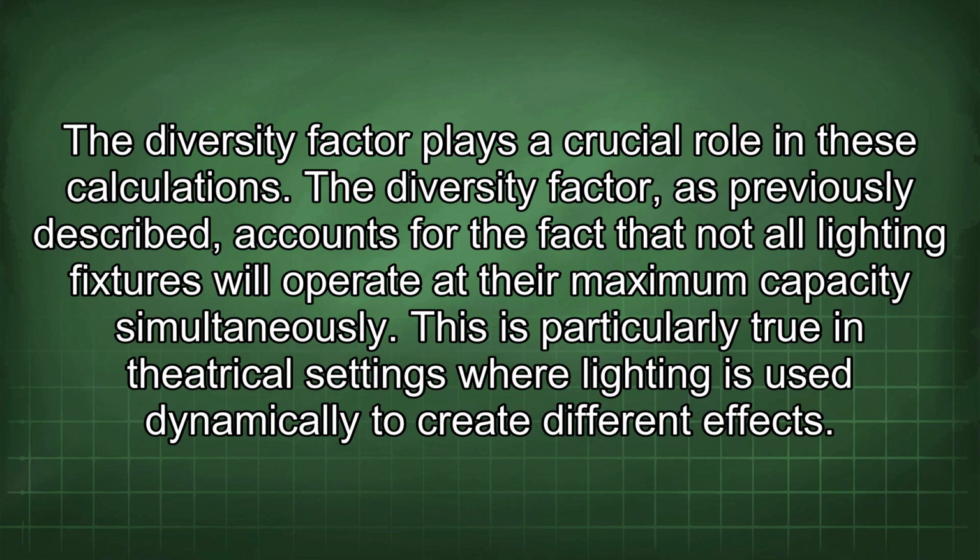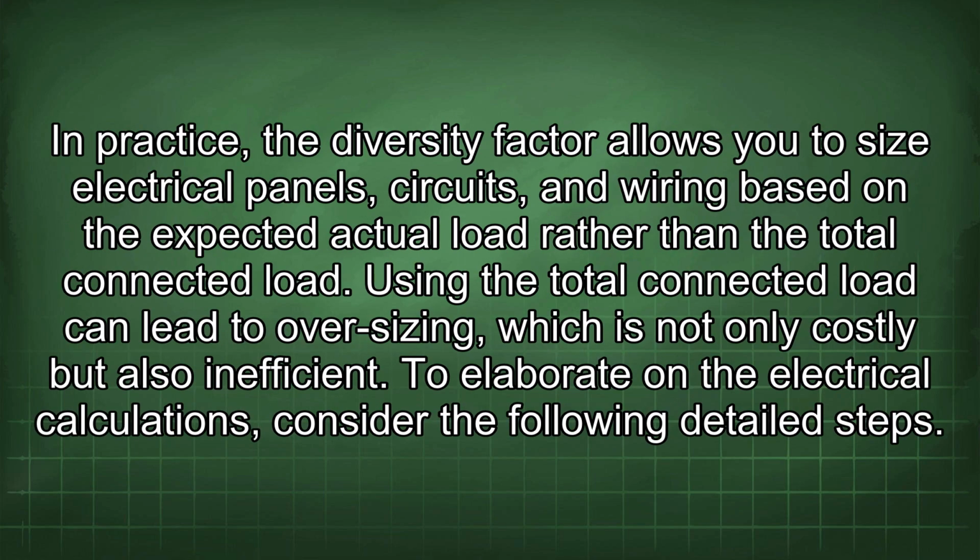The diversity factor, as previously described, accounts for the fact that not all lighting fixtures will operate at their maximum capacity simultaneously. This is particularly true in theatrical settings where lighting is used dynamically to create different effects. In practice, the diversity factor allows you to size electrical panels, circuits, and wiring based on the expected actual load rather than the total connected load. Using the total connected load can lead to oversizing, which is not only costly but also inefficient.